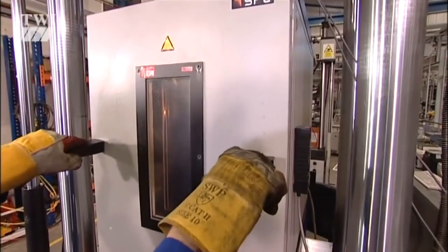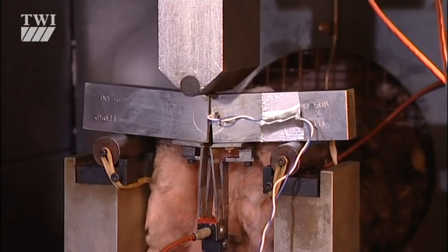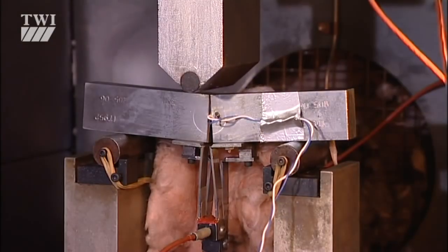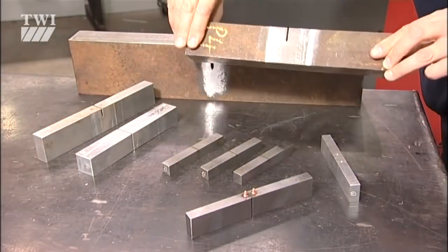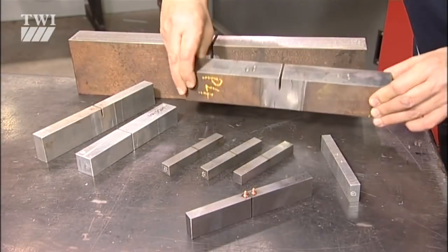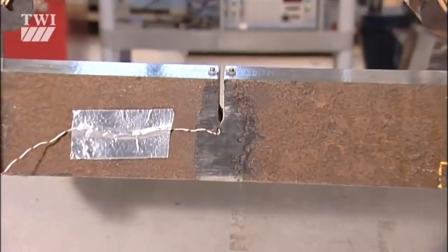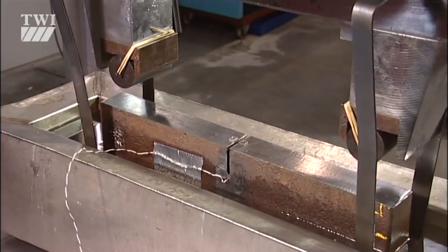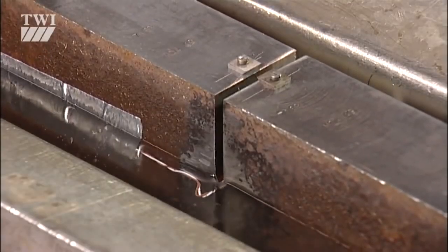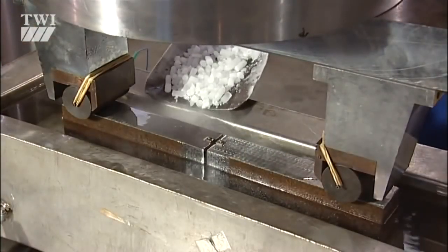Measuring fracture toughness accurately, in a way that can be related to a tolerable flaw size, is a job for the crack tip opening displacement test, or CTOD as we call it. Unlike the small, inexpensive Charpy specimen, the CTOD specimen may be the full thickness of the material. It contains a genuine fatigue crack and will be loaded at a rate representative of the service conditions. As the name suggests, the crack tip opening is measured throughout the test and may be used in fitness for purpose assessments.